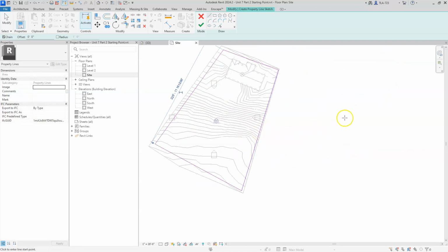complete. It's not uncommon to see property boundaries that fall inside the topo surface you've created, because we oftentimes survey with a little bit of a margin around the property just so that we have a little bit of fudge room in case something is there that we need to indicate or whatever.